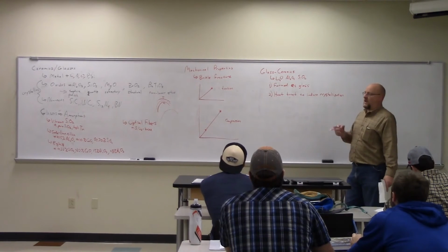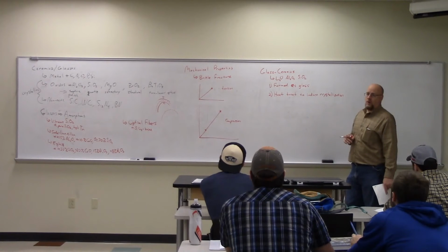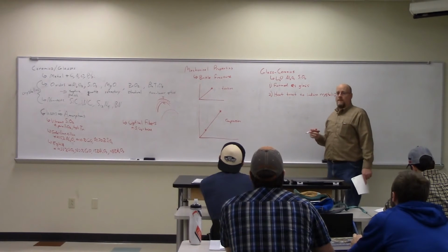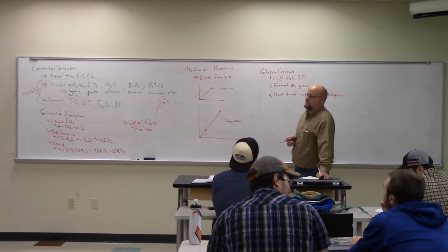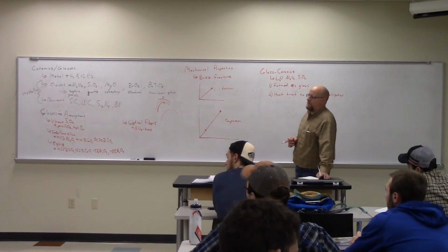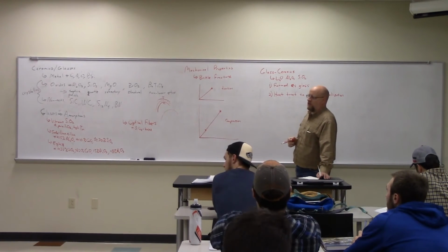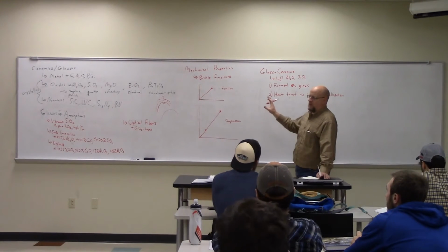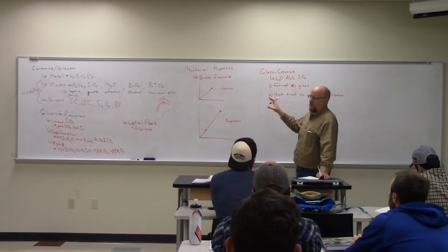But you just can't see through it, and you can't easily form it. You can make quartz windows, but it's very expensive. So when you cross-hatch grain boundaries, that prevents cracks from propagating? Yes, but this is a brittle material, so there's no crack propagating and no dislocations propagating, no ductility to worry about.